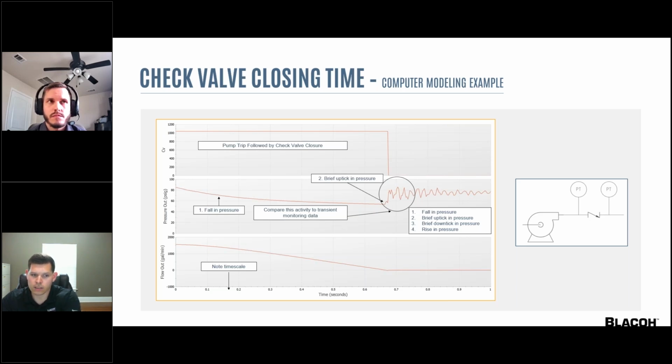It's difficult to see, but that vertical line is not completely vertical, which means there's a length of time associated with it, and it's not just an instantaneous closure. That middle graph is our outlet pressure, just downstream of the check valve. And the bottom graph is our flow rate through the valve. First, look at the time scale. All of these events take place in just 1 second.